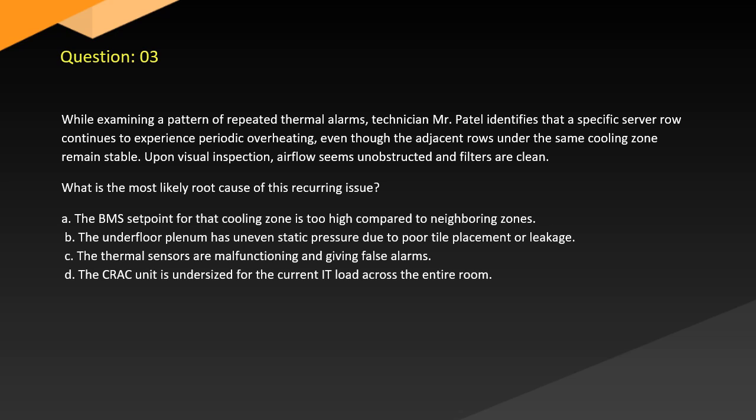A. The BMS set point for that cooling zone is too high compared to neighboring zones. B. The underfloor plenum has uneven static pressure due to poor tile placement or leakage. C. The thermal sensors are malfunctioning and giving false alarms. D. The CRAC unit is undersized for the current IT load across the entire room.